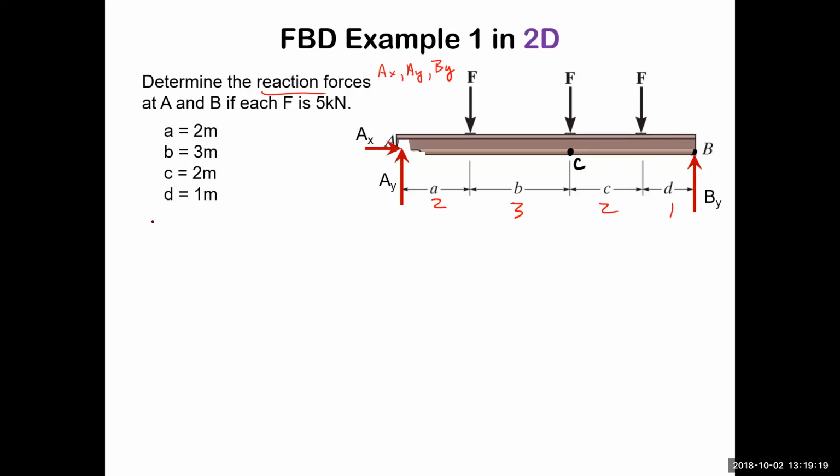And we've been telling you that the most common equations of equilibrium are the sum of Fx, the sum of the Fy's, and the sum of the moments about some point equals 0. That's the most common, but in this very first problem, we're going to do the second most common, which is taking moments at different places. It turns out that that's actually quite easy too, because the sum of the moments at 2 different points can give you these two vertical forces, AY and BY, with less algebra.